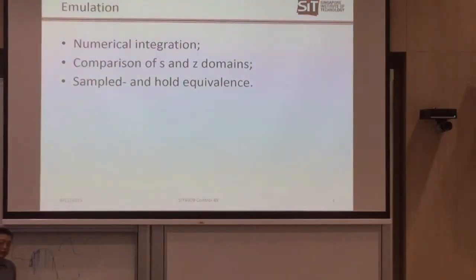And this is something we call emulation. And emulation is basically, we understand that in digital control there is no continuous function. There is no differentiation, no integration, no S function. We only have difference equations. So we learned about 1 month ago: give you a differential equation, give you integration, give you PID, give you continuous modeling, you are able to convert your differential equation to a difference equation, right? And that is very helpful if you are doing engineering.